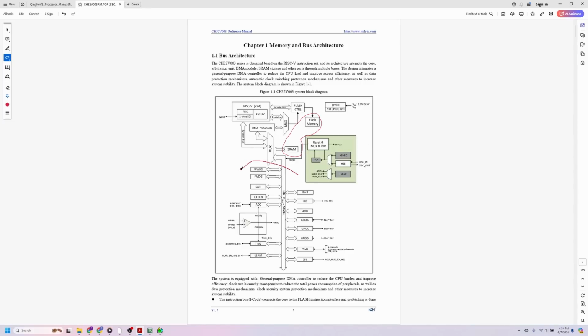Another point I'd like to make is that microcontrollers are far more than just their processor cores. They also have memory, peripherals, power systems, clocks, and so on, and those can actually be more important than the core itself. The ARM versus RISC-V debate doesn't actually tell us anything about these peripherals, and the majority of the time these aren't going to be open. The differences in peripherals also mean that programming various RISC-V or ARM parts, even with the same core, can be very difficult, as there's not really any standardization of these.